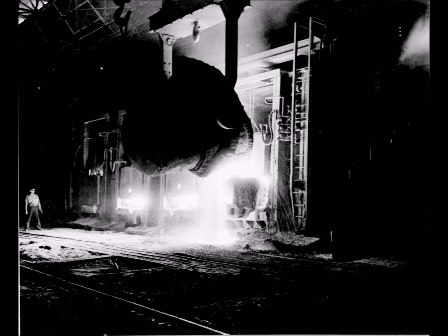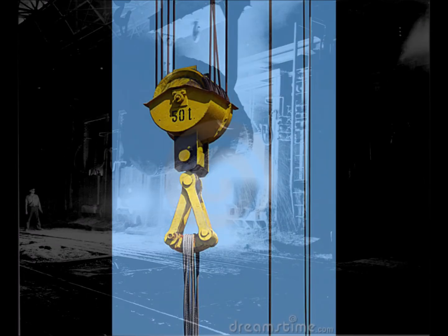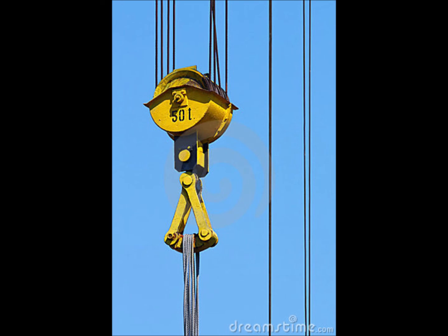We also see, for example, in the sense of cranes, even though we're dealing with much, much greater force now, we still use this notion of block and tackle. The reason that we do this is that it keeps the cables thinner, so they bend easier. And then we strand the cables as well, so when they go around a corner, they don't have the rigidity of a bar.